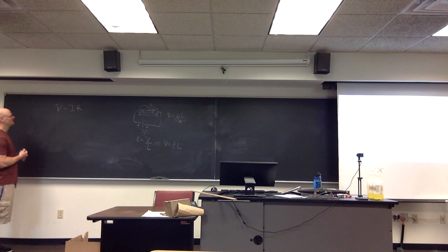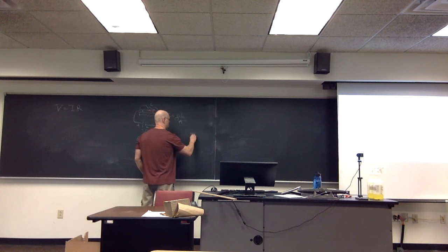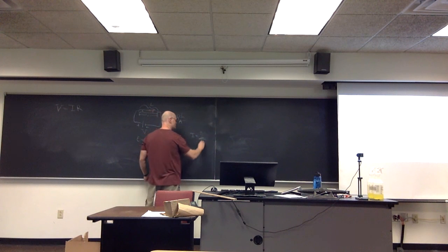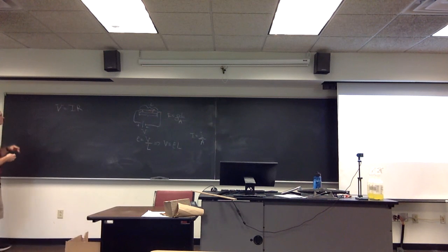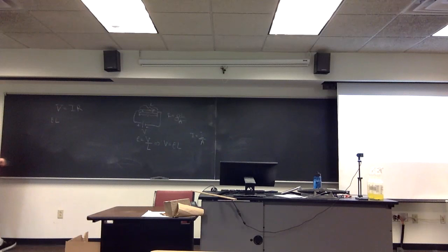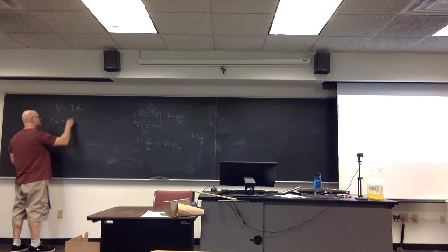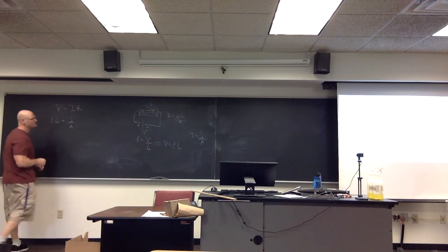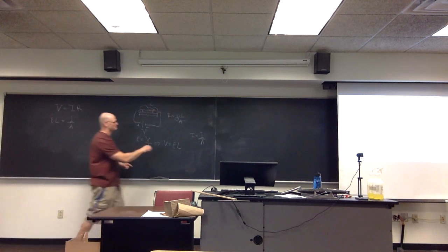So, we also know now that the current is simply equal to the current density times the cross-sectional area. So let's use all these things and put them in here. So what this says then is I can rewrite the left-hand side as simply the electric field times the length of the wire. The right-hand side then becomes the current density times the area. I'm sorry, that's backwards.